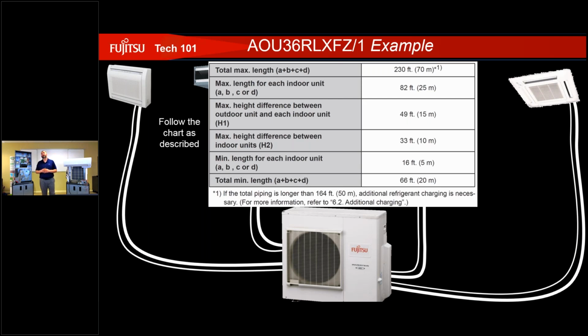If you don't follow those parameters, as Jim had alluded to earlier, they're not going to honor the warranty. These are the measurements of what our compressor is calling for. It has nothing to do with the amount of refrigerant within the system. It's all about the capabilities of our compressor.